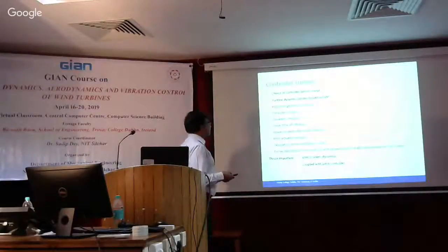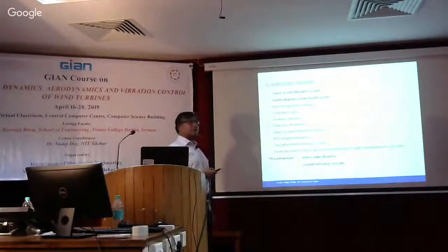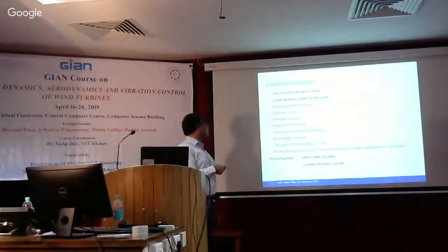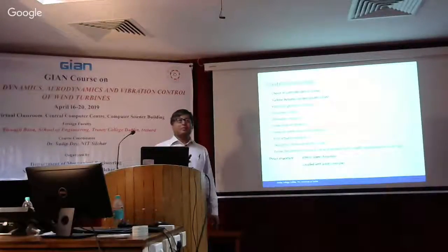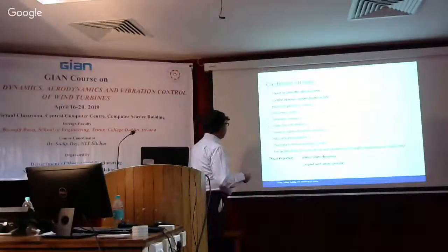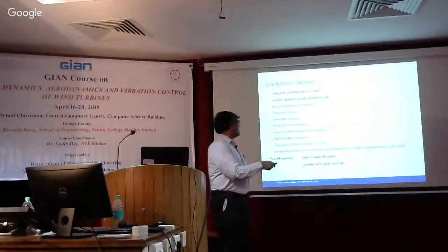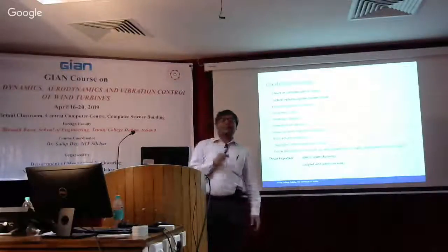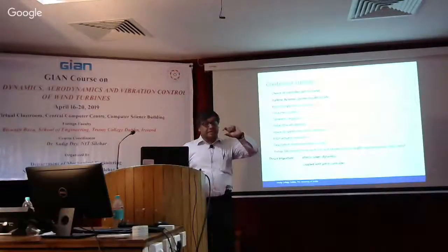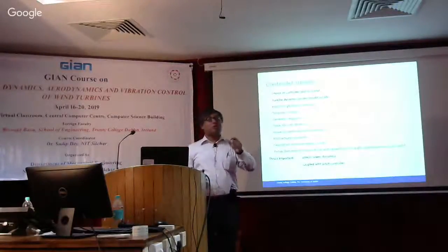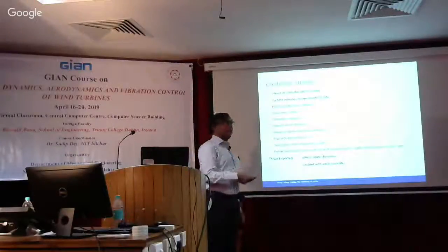Generally, when you're designing the pitch controller or the control systems, you should also take into account the dynamics of the turbine, which is the rotor and the generator rotation, drive train and torsion. Generator response is very important. Tower vibration, power and speed transducer responses, and the pitch actuator response itself, because the actuator also has dynamics. Then there's the description of the aerodynamics, which you have seen, and the partial derivatives of the torque and thrust with respect to pitch angle, speed, and rotor speed, which will allow us to apply the controller. Because if you're applying the controller, you need to know, if you change the torque or pitch by a certain amount, what impact it will have on various effects on the turbine.